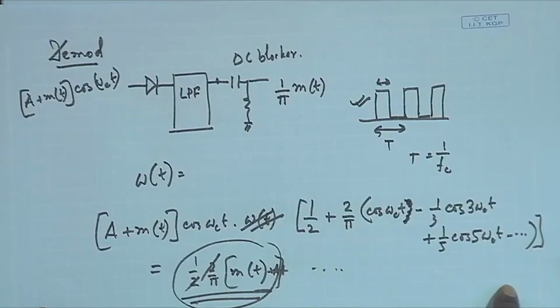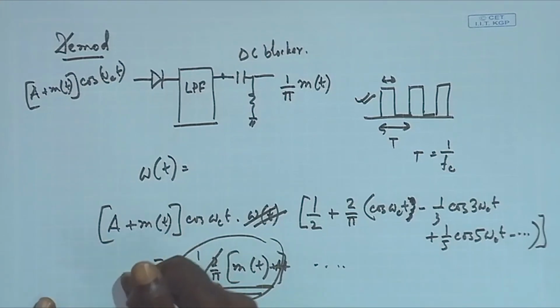So the Wt I will be multiplying is no longer periodic, it is a random signal now, because where that crossover will be happening I do not know, that depends on the signal. So anywhere it can happen, and that completely breaks the periodic nature of Wt. At that point I cannot write my Wt as this one very nicely. So therefore that multiplication I was getting, I am not sure of now, and that is the reason why I will not be getting my signal back if I just put a diode.